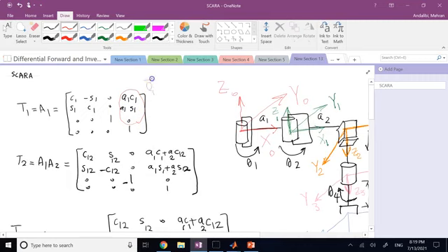And this is your Z number 1. Now pay attention that these calculations might look a little bit too much and intimidating sometimes, but for a computer, if you program them very nicely, they are nothing. For a computer that can carry out all these matrix products and read your DH table, all you need to really give to your code is the DH table.